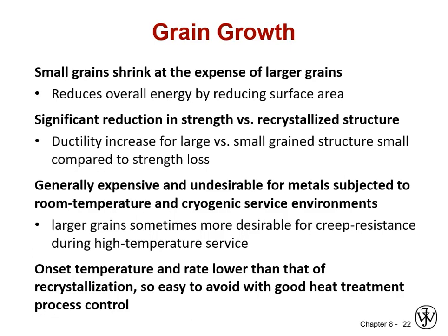And of course, if you're looking at the cost of your process and its energetic requirements and sustainability, there's never a reason to be consuming the energy that is required for these thermal processes for metals or ceramics any longer than they need to be. So do not leave your parts in the furnace too long.